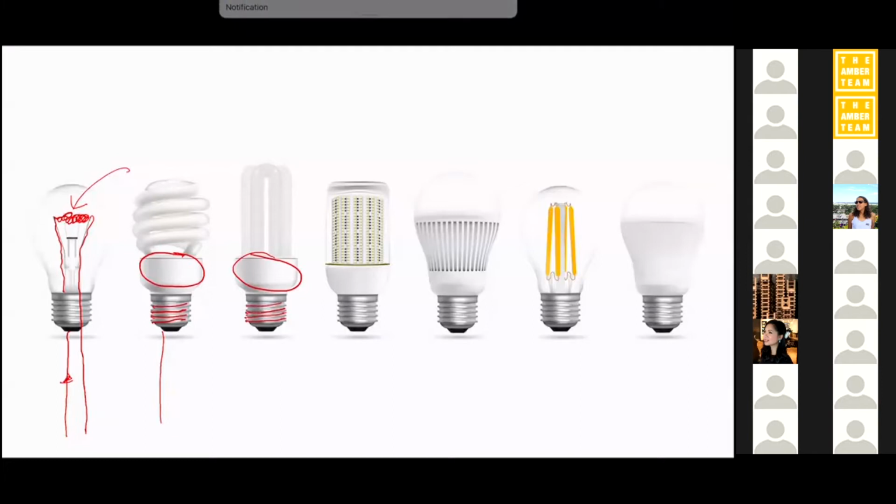And we don't have to have the equipment to regulate the current, because what happens in a fluorescent lamp is we have a tube with phosphors in it, which are like a little powder, and it's got a gas in it also. We excite the gas, and the gas makes the phosphors light up, and that's what brings us the light in fluorescence. In the case of ballasted compact fluorescents, compact because they're small, ballasted because they have this equipment here.